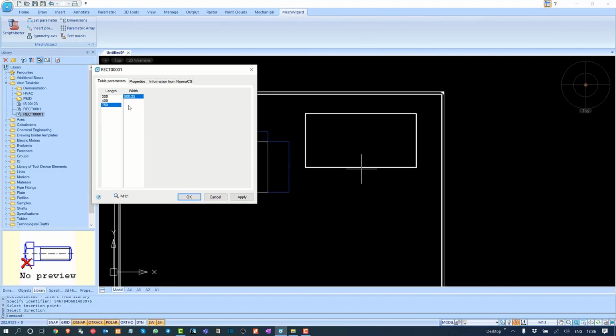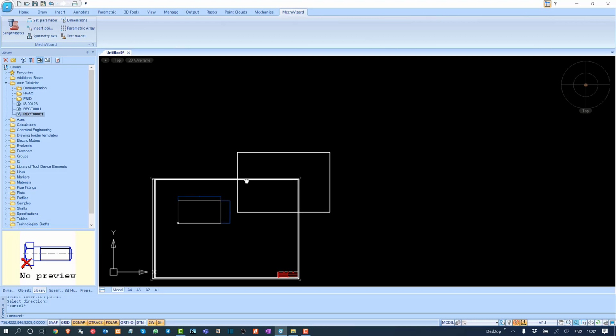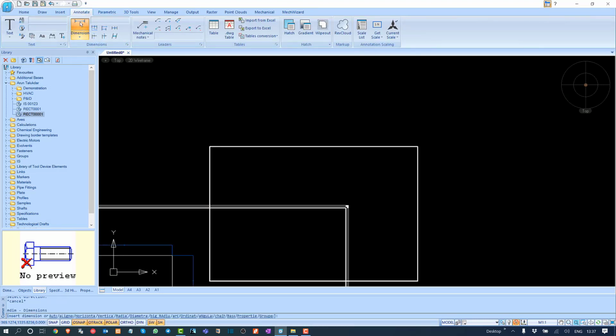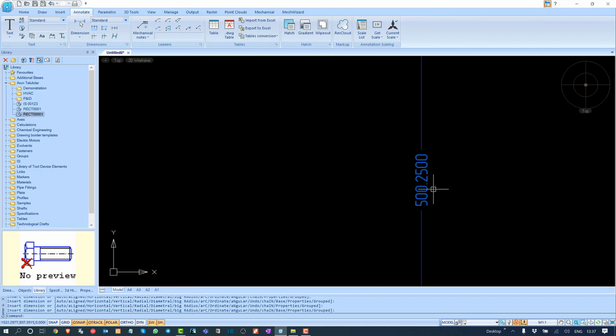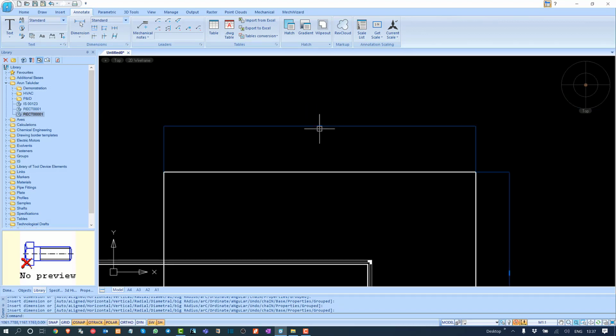Can you see, if we click on the length, the corresponding width will be shown here. So now, if we need to create a length of 750, the width will be 525. So I'll click OK, and I say OK. So it is now bigger than before. Now we should go to annotations, and we want to dimension this, measure this, and see the value, right? As you can see, it's 502.25. So this is very good. And this is 750, right? Very good.